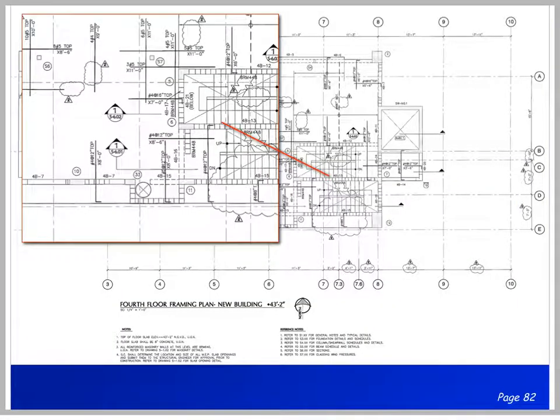Okay, let's take a little bit closer look at the plan we were just reviewing. And you can see here that we've got number 4s at 8 inches on center top. Here they're showing number 4s at 12 inches top along here by 8'6" long. They've got a number 5 at 12 inches on center by 8 foot long with a little hook bar. So anyhow, it's an interesting way of trying to delineate the rebar on a plan.